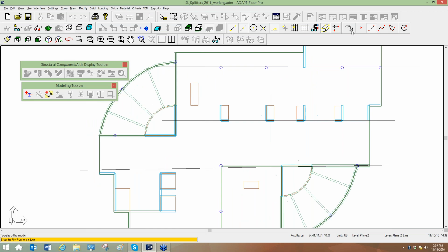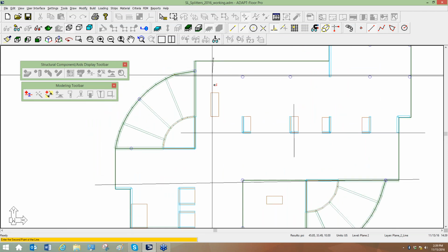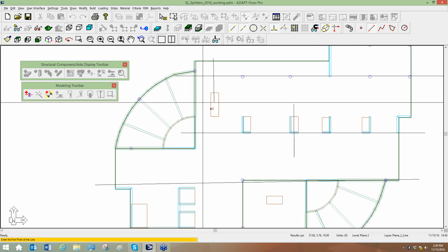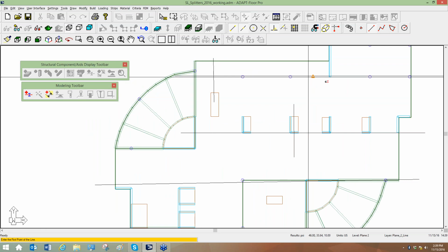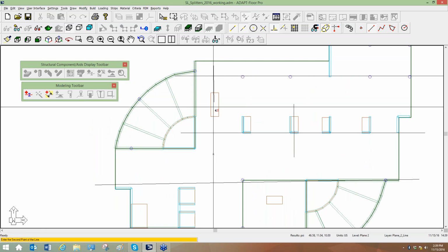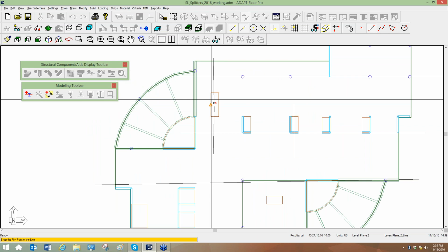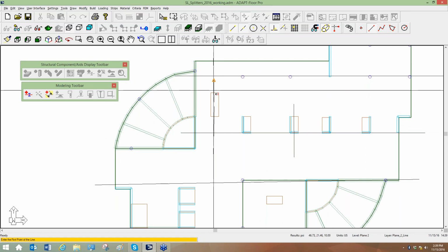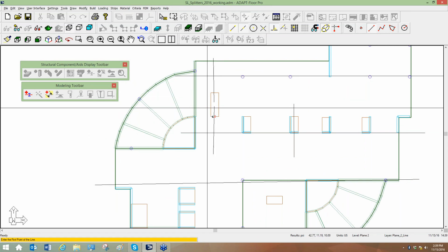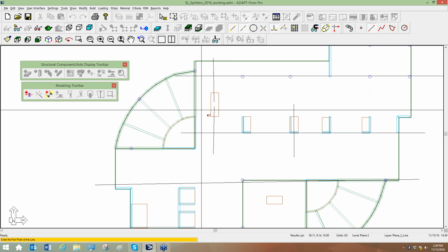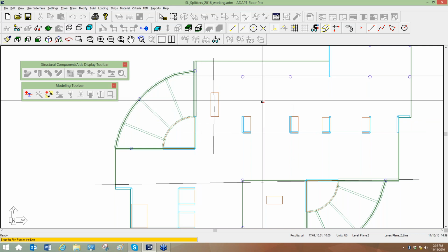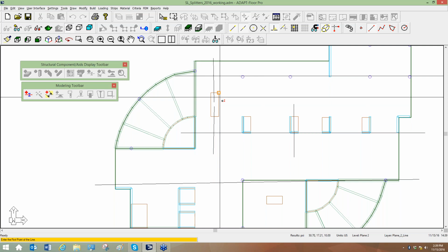So over here we have a design cut which would look something like this. It would extend into the opening along this support line, and along this support line it would extend into the opening, but it doesn't extend out of the opening. So this is okay. This particular opening that's in between the two support lines technically does not require any splitters.